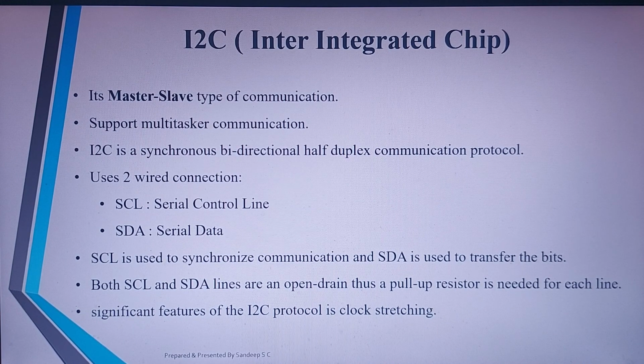In such a requirement, the I2C protocol can be used when we want to communicate between the ICs on the same board. This basically works on the principle of master-slave communication. One device will operate as a master and other devices will operate as slaves. Here we can also have multiple masters. Masters are the ICs or modules which initiate the communication. Slaves are the ones which respond to the masters. So this protocol supports multi-master communication.